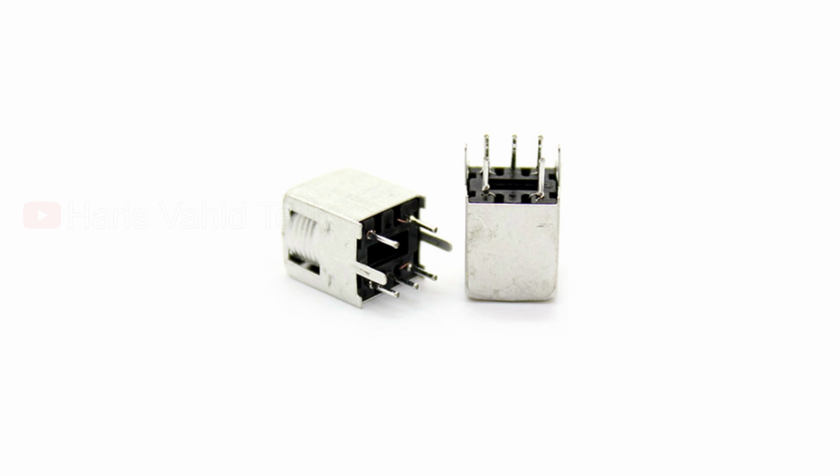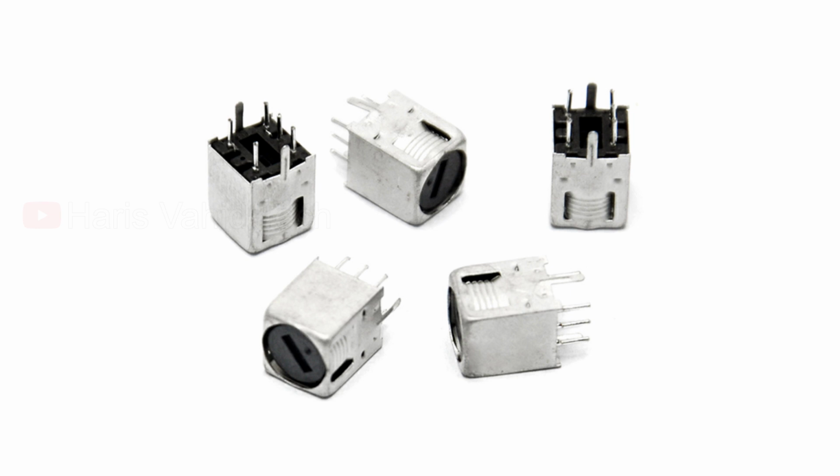And the main reason for using an intermediate frequency is to improve frequency selectivity. In communication circuits, a very common task is to separate out or extract signals or components of a signal that are close together in frequency. This is called filtering. An example is picking up a radio station among several that are close in the frequency range. Application: IFT transformers are also used in the intercarrier TV receiver sound section of television. Perhaps the most commonly used intermediate frequencies for broadcast receivers are around 455 kHz for amplitude modulation, that is AM receivers, and 10.7 MHz for FM receivers.